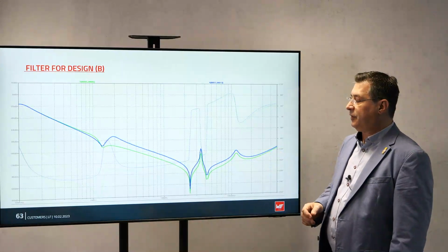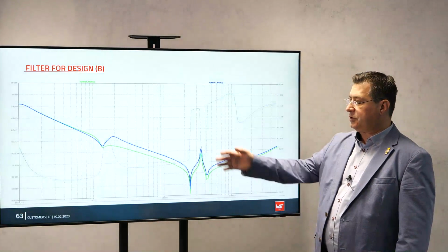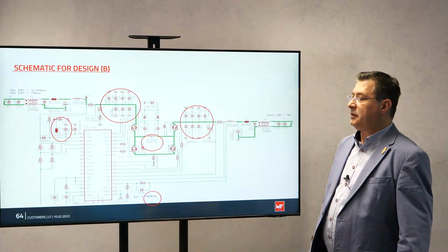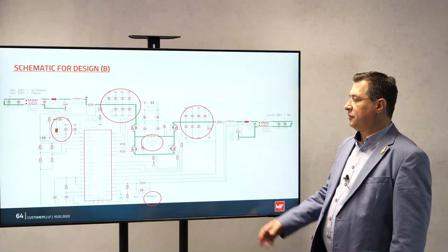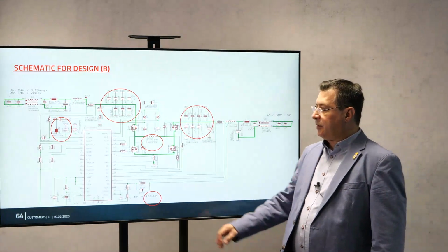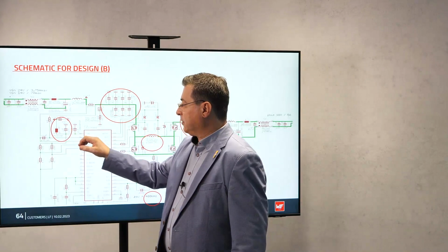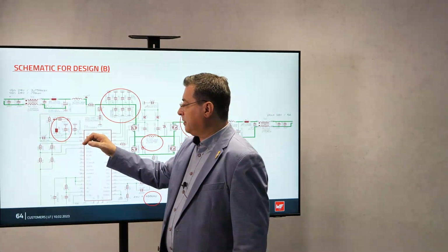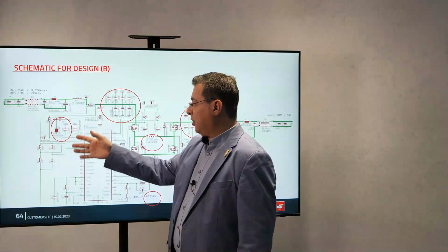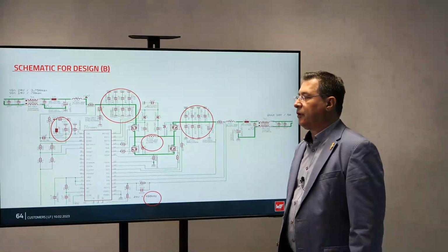Now, this is how the filter looks in his simulation, which is more like 50 dB damping, so looks very good. And this is the final decision of the capacitors, the input-output capacitors, and additionally these chip bead ferrites on the VIN on the chip, because it's also important to filter so that you don't have your own EMC problem already on the controller.